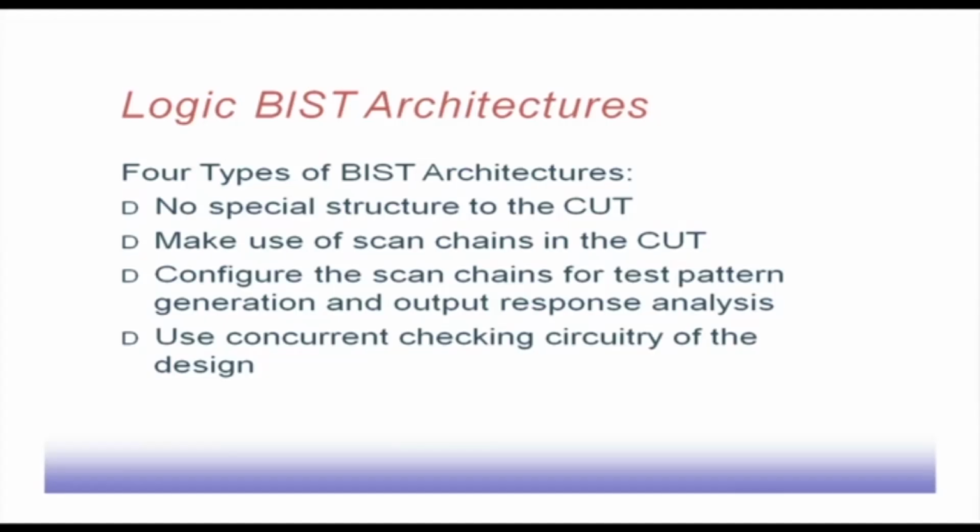And in the response analysis, there is also some summation, so some XOR gates get inserted in the circuit. So, if we can modify the scan chain so that when required it can act as pattern generator or response analyzer, that can be done. If it is done, then this is going to be useful, or we can use concurrent checking circuitry of the design. That can also be done.